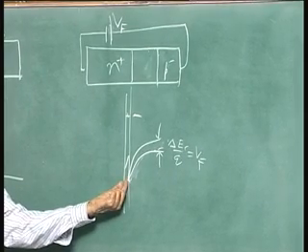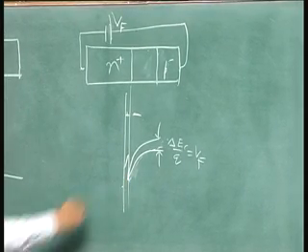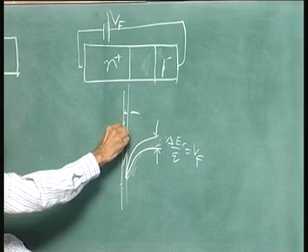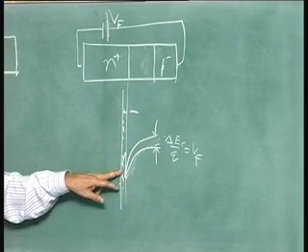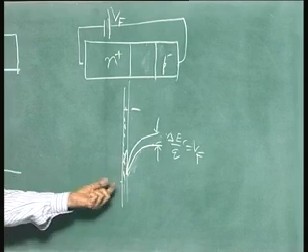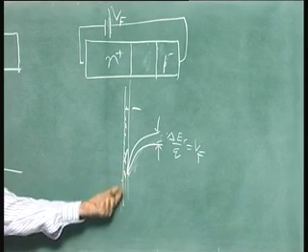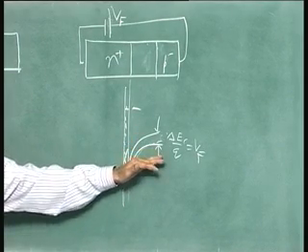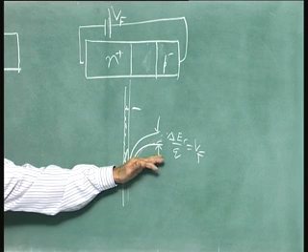What about here? That also falls down slightly, because the charge is very high there, so you will not notice the change in the depletion limit so much. So mainly the whole effect is felt on this side in an n plus p diode.